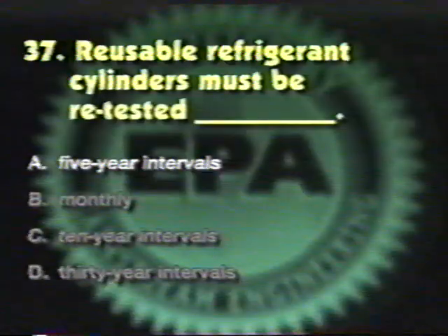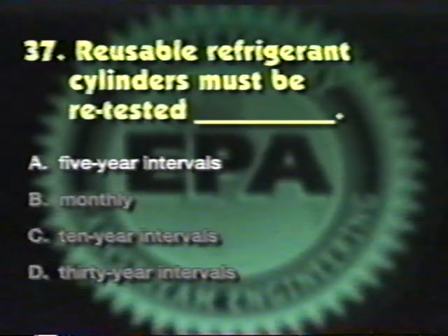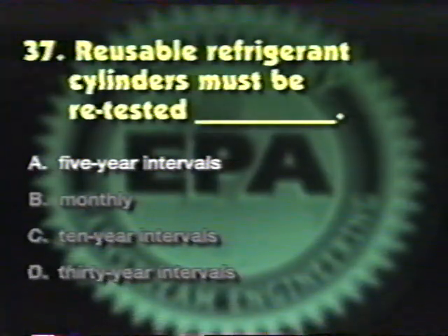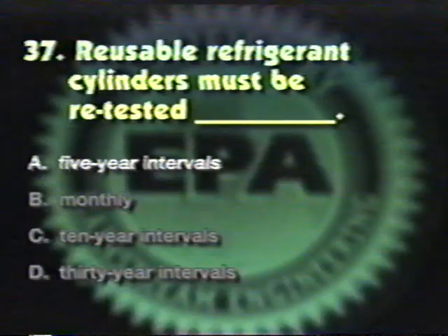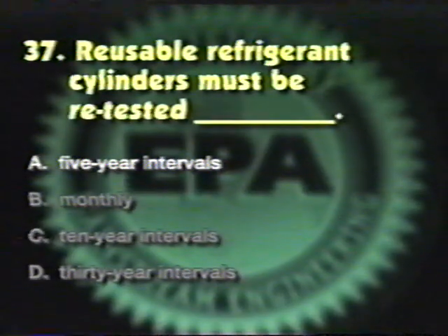The answer is A. Reusable containers for refrigerants that are under a pressure above 15 psig at normal ambient temperature must be hydrostatically tested and date stamped every 5 years.